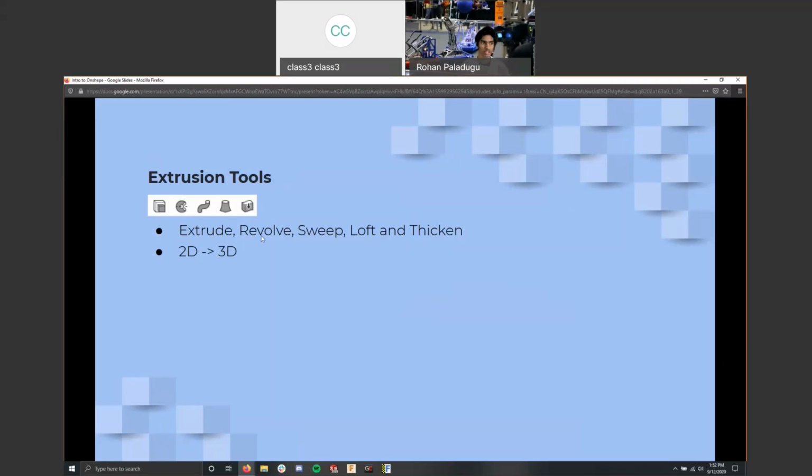And then another common one is the revolve. Let's say I wanted to make a shaft by hand, a circular shaft. How would I do that? Well, if I were to cut a shaft and get the cross section of it, you would see that it's a rectangle. So I go ahead and draw my rectangle, dimension it, everything's good, and I exit out of the sketch. Now, how do I turn that rectangle into a shaft, a cylinder?